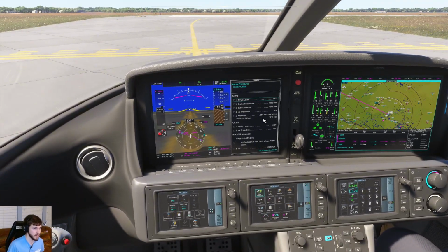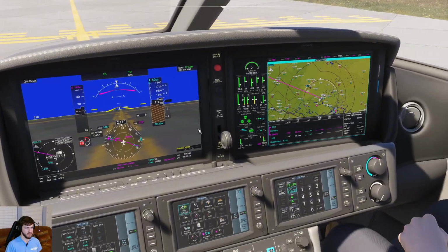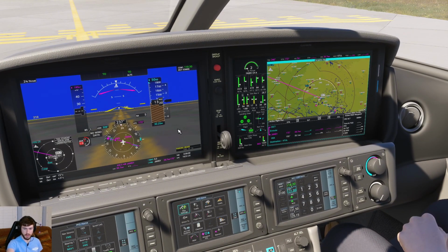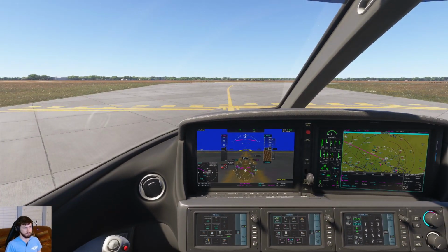So before takeoff checklist is complete, our departure is briefed. That's all good. Next will be the climb checklist there, but I'm going to go onto the full PFD there. We're going to switch to tower, and then 134.85 will be next for the departure frequency. So I've got that in the standby, and we're ready to go. I'm going to go ahead and call tower and let them know. Wichita Tower, November 891 Sierra Bravo, holding short, runway 32, ready for departure.